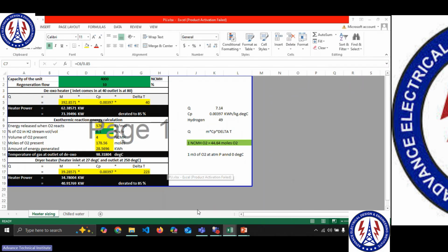Yes. Okay. So this calculation now, I need to check again, it is the simple equation. So two equations that you need to study in the whole course: one is heat supply, that is MCP delta T, and the other one is the pump equation, QH rho G divided by 1000. Two equations. M we know, CP we know, delta T we know. Based on what is the required item, you know the CP. You can just put it on the internet anywhere. It is there. Just check if the units are correct.